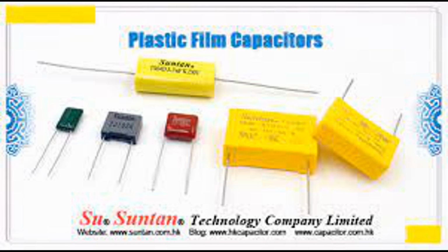The plastic film and electrodes are wound into a cylindrical roll or sometimes a flat pack, also called stacked. The windings are tight to ensure compactness. This winding process creates the layered structure where alternating layers of the dielectric and electrodes are arranged. 4. Connection to terminals. The ends of the windings are sprayed or connected with metal, usually zinc or aluminum, to form contact points with the electrodes. Wires or terminals are attached to these contact points for electrical connection to a circuit.